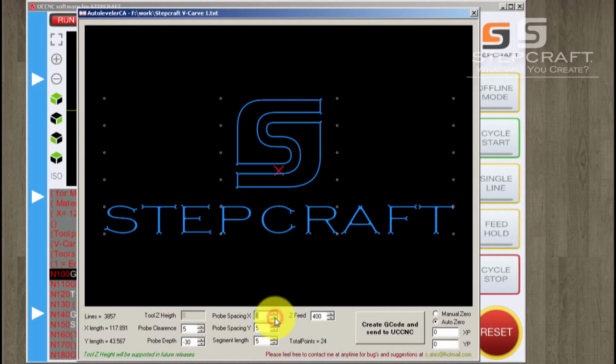If you lower this, you're going to have fewer points, as you can see in the image. The more points you have, the better the quality of the mapping of your surface. If you only want to engrave, or if you want to level the surface, maybe fewer points are going to be needed. But we're gonna engrave on a very spherical surface.